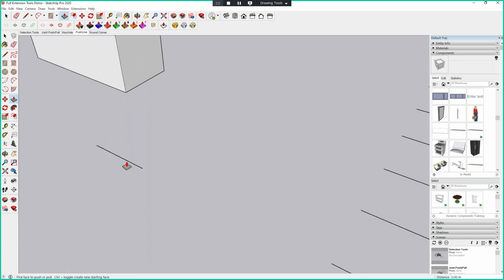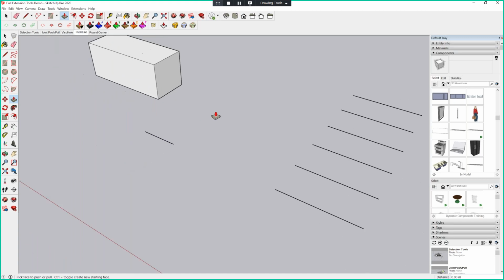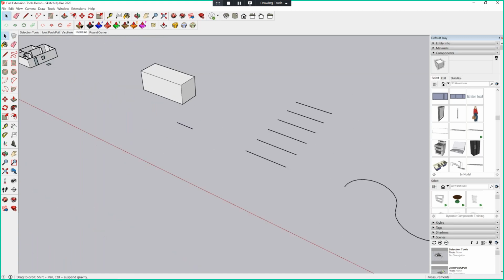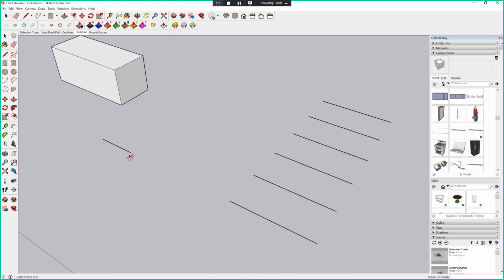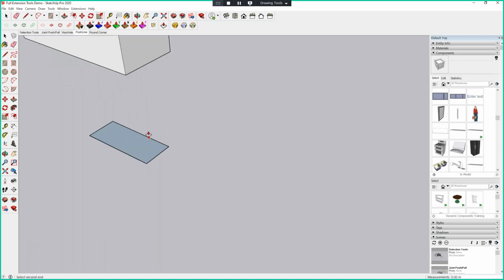However, you are not allowed to push-pull single lines like the ones we have here. What push line does is a very simple thing, but I find it such a handy tool to have: it push-pulls your edges to create surfaces. It's kind of like a sister function to the native push-pull tool, but you can also just type 2 meters and create push-pulls in any direction that you want.